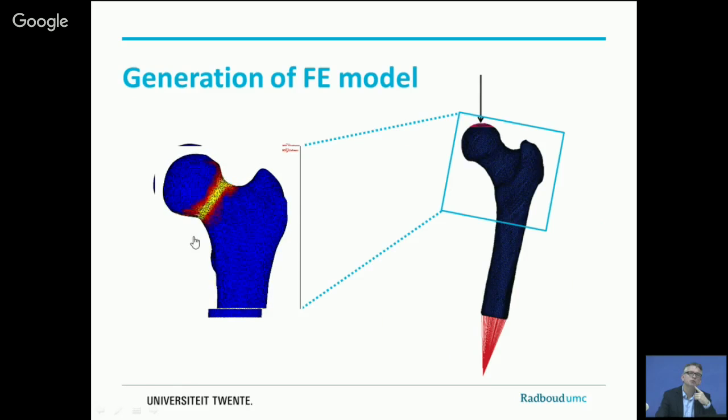So you can see here that the material becomes plastic because we load it beyond the yield strength. And if it becomes plastic, you can imagine first one element becomes plastic, and then that kind of crack propagates through the whole bone, simulating a patient that ends up with a fractured bone.